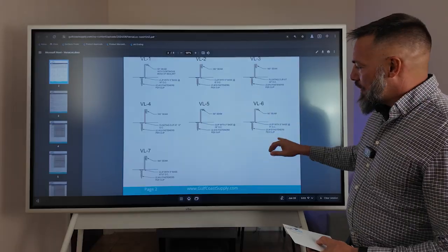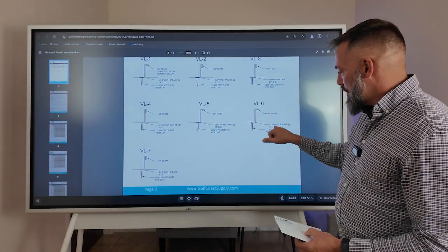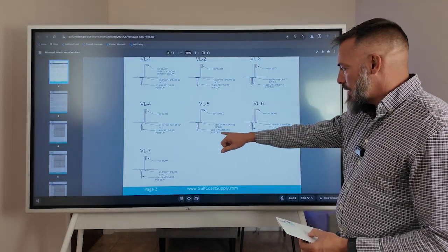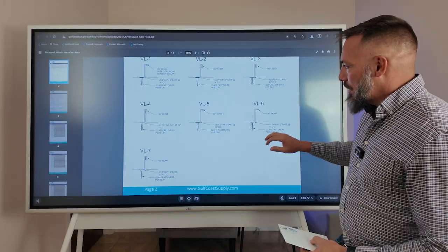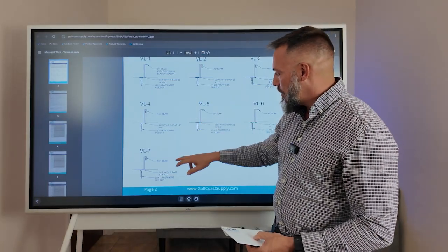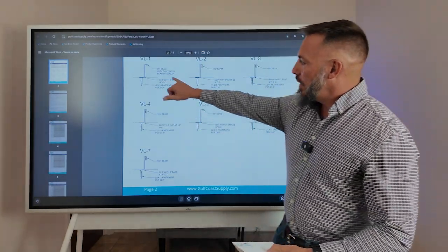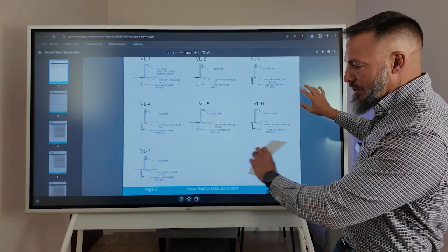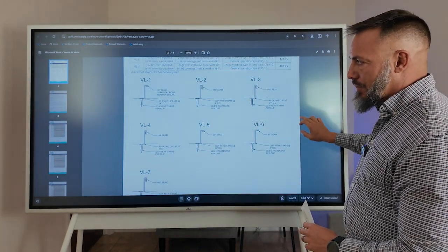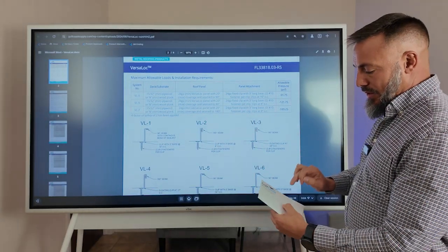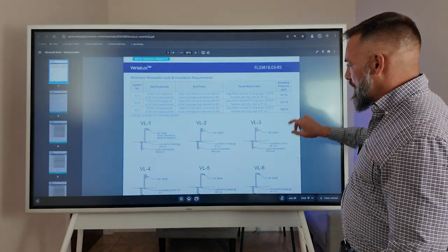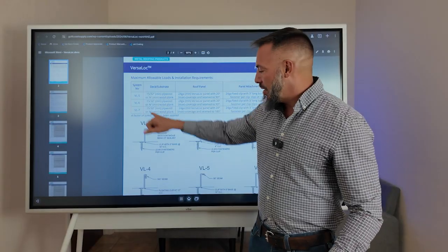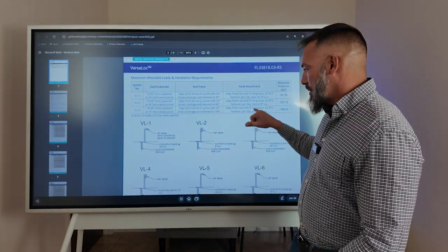So if you need to know what all these are, each will tell you clip spacing, 3-inch base, 8-inch on center, 2 fasteners. There's some in here, 90-degree seam. There'll be some that'll tell you with sealant, with continuous bead of sealant in that leg. All these are just different fastener patterns that you have to use to get to the pressure that you need. So here's your pressures over here. This will call out, like VL5 will be VL5, and then it'll also call it out here.